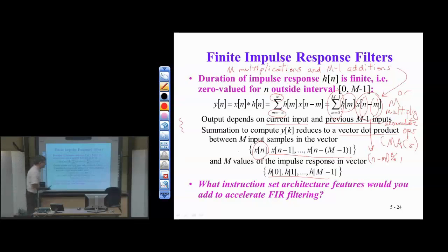The modulo addressing is part of the instruction set. It's part of one of the addressing modes, so that's no overhead. There's no delay to use modulo addressing on the C6000. The down counting on the C6000 unfortunately has to be done in software. There's no hardware down counter on the processor. So we'll have to manually decrement by 1 and then loop if the counter's not 0.